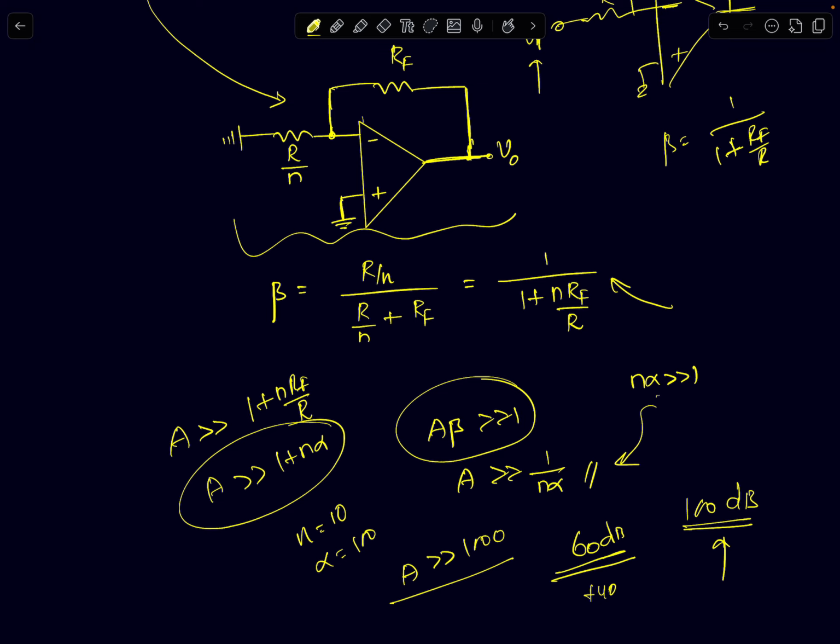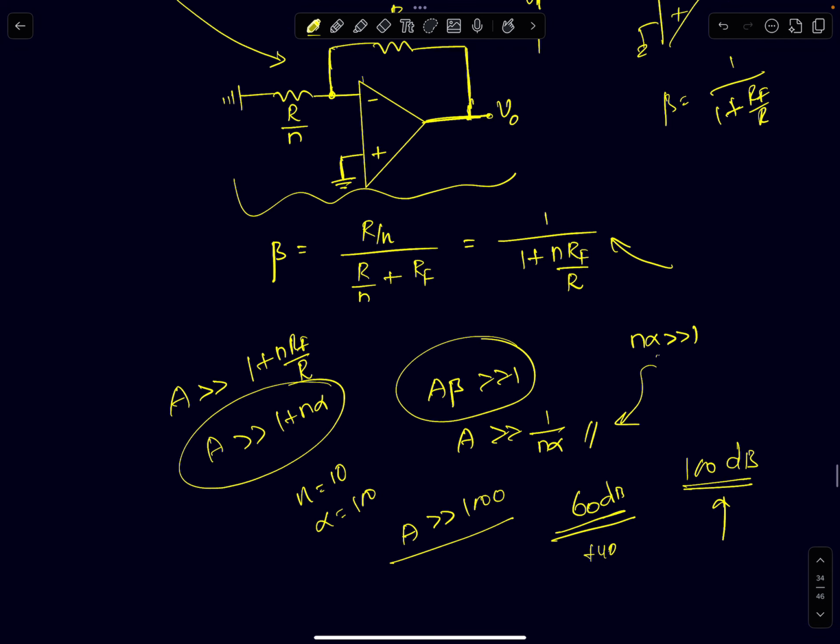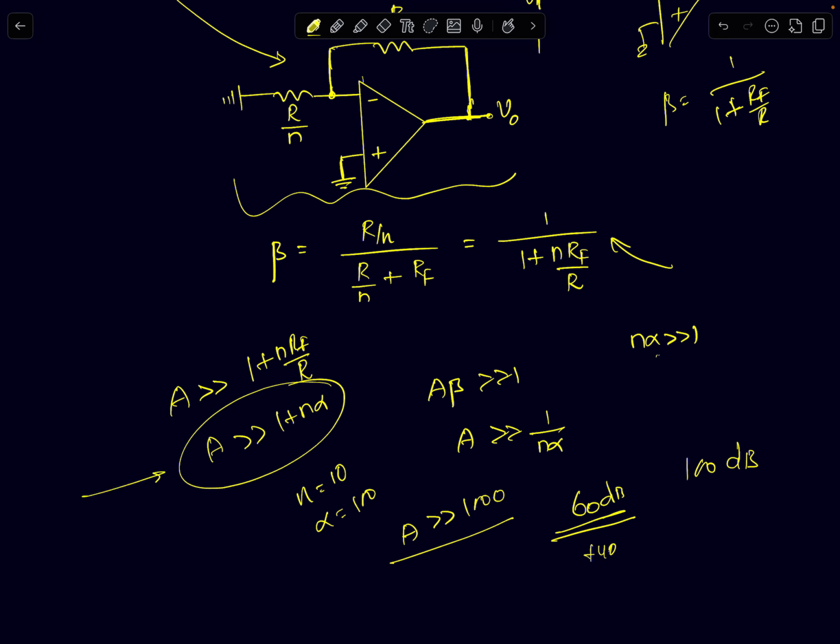That is if I were to ask you to find the DC gain. But we are interested in finding the bandwidth, the UGB of the Opamp, or what should be the constraints for the Opamp. That's what was asked in the question. DC gain, we didn't bother in this question. But if DC gain was asked, I'm just telling you how you arrive at that condition. If you're going to use this adder, you will not pick an Opamp whose DC gain is smaller than 100 decibels.